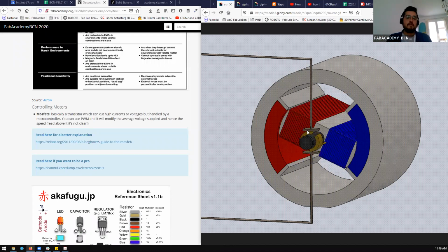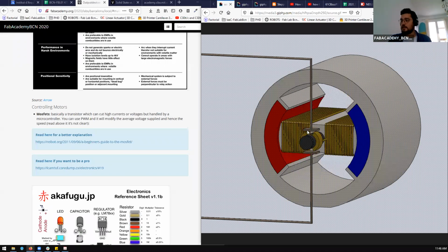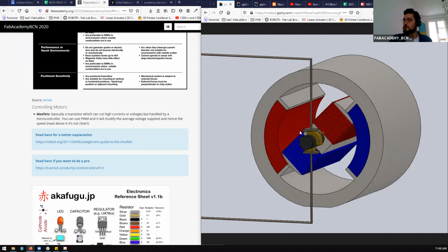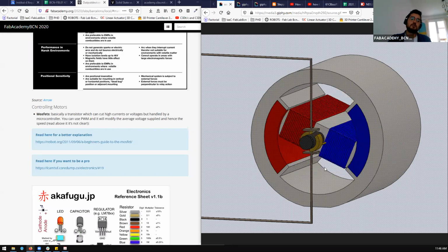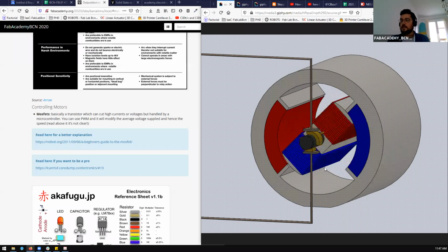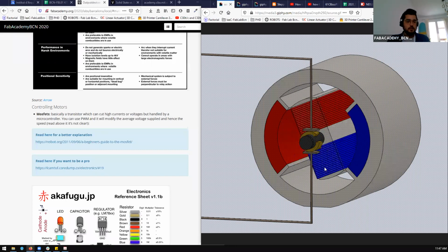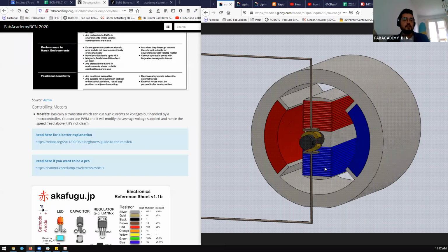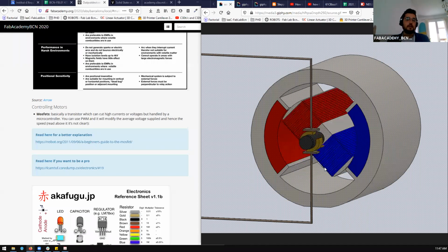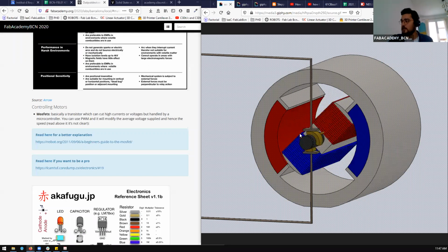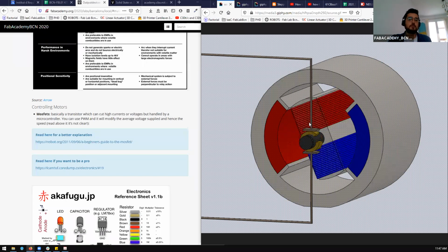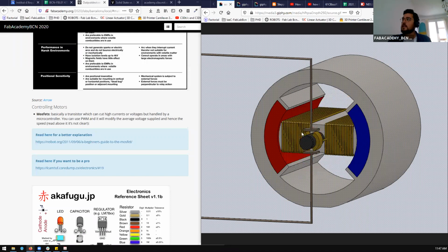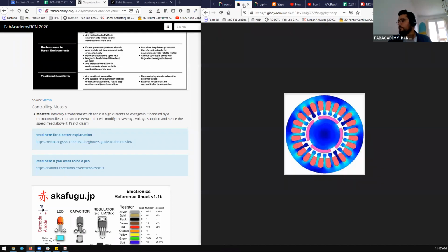They are usually made of graphite, reinforced graphite and steel, and those pads get wasted. So actually the life cycle of a DC motor is short compared to other motors. They cannot rotate endlessly, because they have some friction parts that are those brushes, and those brushes, depending on the size of the motor, can be replaced or not.